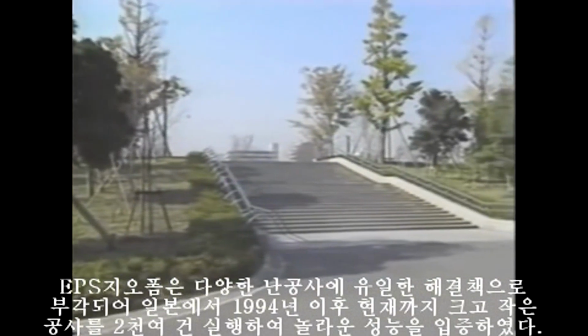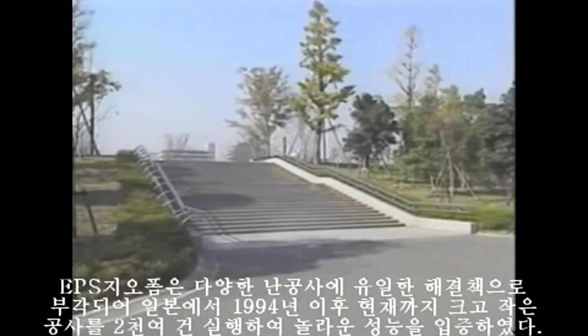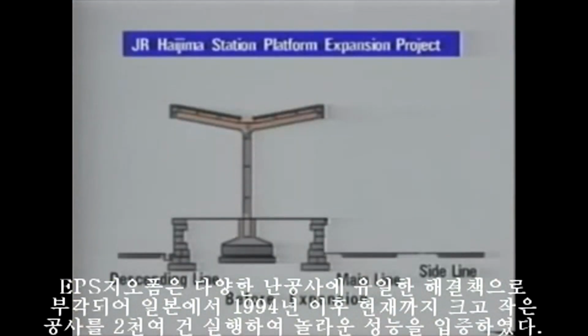The Suru Imperial Gift Park and Kiba Park area is situated on weak ground formed from an alluvial layer. The EPS construction method was used as a countermeasure against settlement due to ground consolidation. In this situation, lightweight EPS block fill positioned on weak soil was utilized to construct artificial landscape and to create a scenic area. On top of the EPS, covering soil was provided for the various trees, shrubbery, and flowers to make the park attractive.